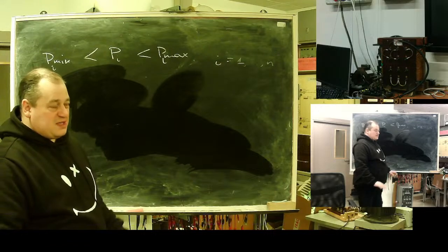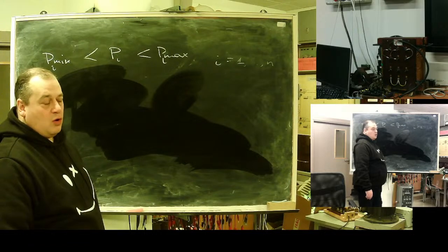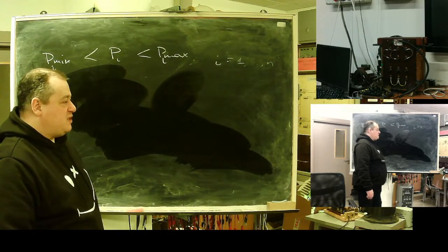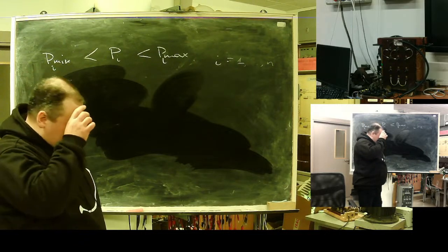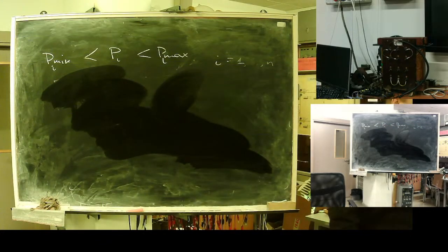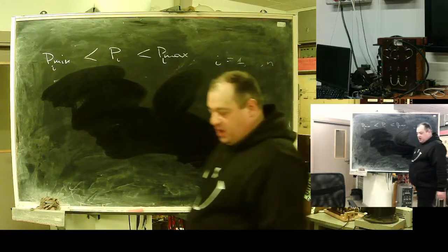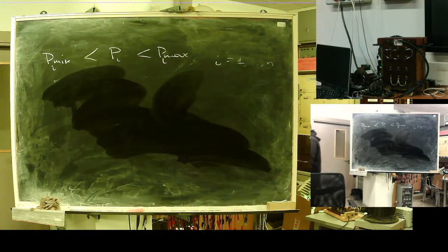For small turbines it's not so vital, but for large power, low speed turbines, for turbines with heating, this heating diverts from the second stage, it is vital to maintain minimal steam flow through the low pressure stage. They are large in diameter and with very small tolerance, any disturbance in thermal regime may lead to mechanical damage.